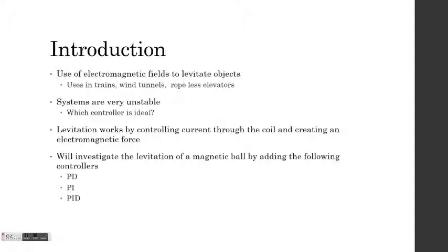The transport methods that use magnetic levitation move the vehicles along a guided track without making contact with the ground. The magnets are used to create both lift and propulsion, thereby reducing friction and allowing very high speeds. In itself, maglev technology includes no moving parts. This system can be used with trains, ropeless elevators, and many other modes of transportation.